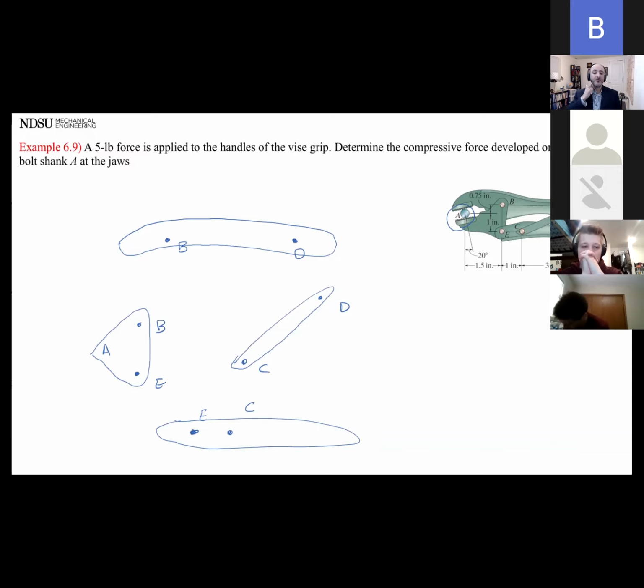Step 2 is to put on active forces and reactive forces, but we're going to do it one by one while keeping an eye on where the pins are going to go together. The reason for that is, as I explained last time, if I want to have a force on this one, because this is a 2-force member, let's call it FCD. Then I know that point C is going to have FCD, and point D is going to have FCD.